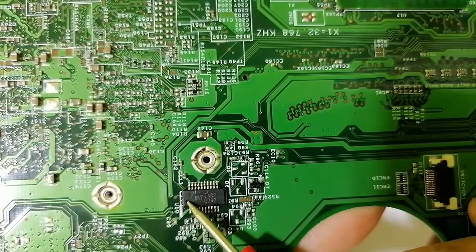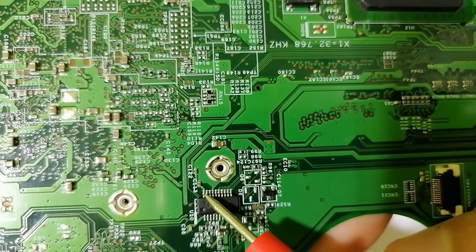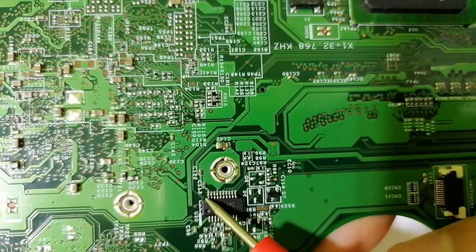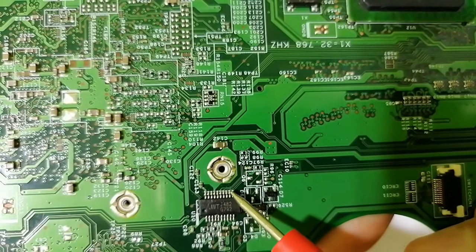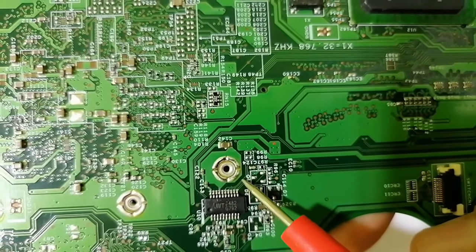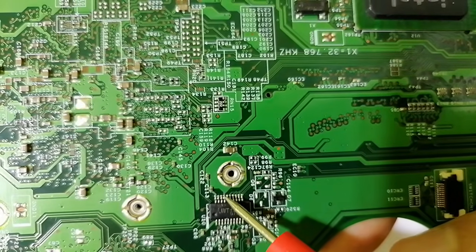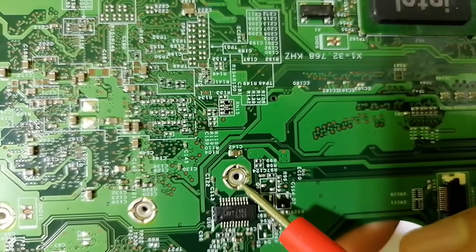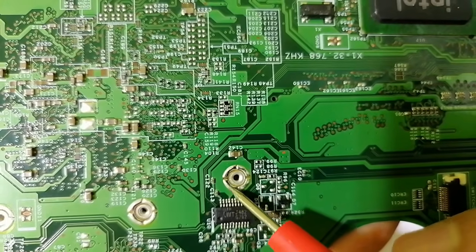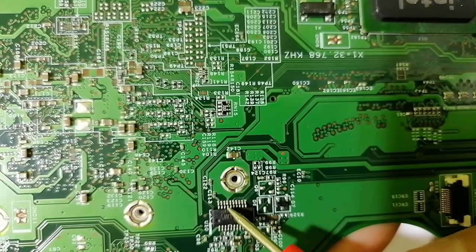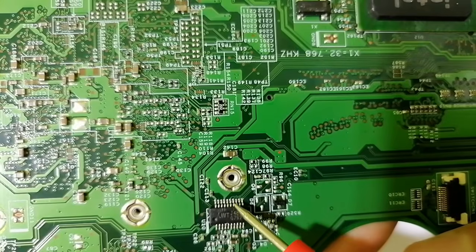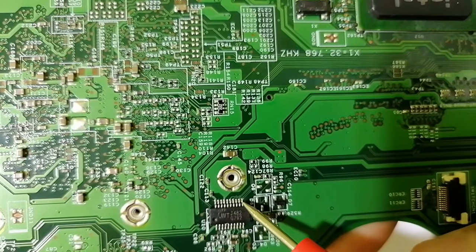Guys, this is basically pin number 1. Do you see in this pin we have a bolded line, means here it gets input voltage, the power in. And over here, do you see the signals? These are just enable signals and control signals. And over here also we have a bolded line connected to this hole, means over here we have ground. So this pin is for ground, this pin is for power, and those are just control signals.